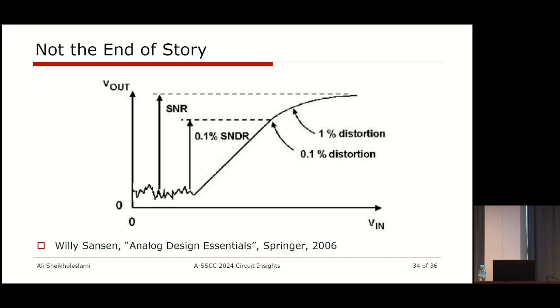When the input signal becomes very small compared to noise, essentially what you see at the output is noise, right? That is initially, and that is the concept of SNR in that case. But then when you go ahead and increase the input, you start to introduce distortion. I can see this nonlinear function that we had, which is supposed to be ideally a straight line. It doesn't go below this because now essentially you're limited by noise in the output, right?